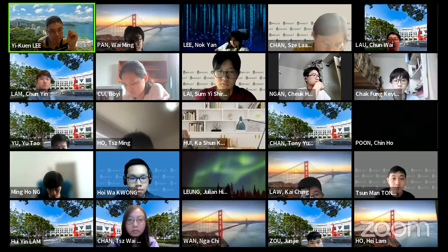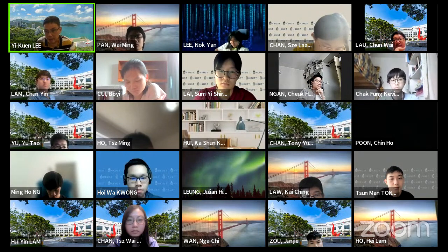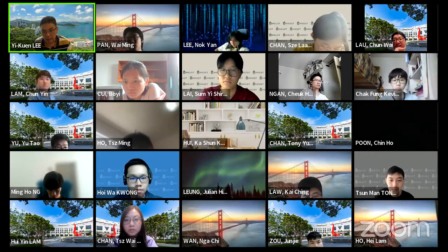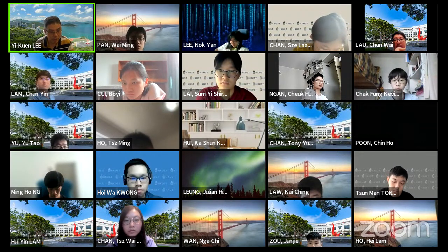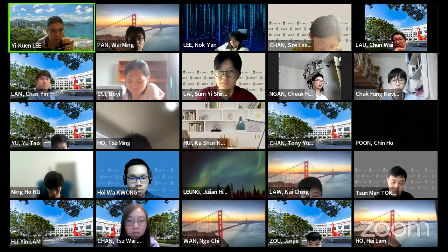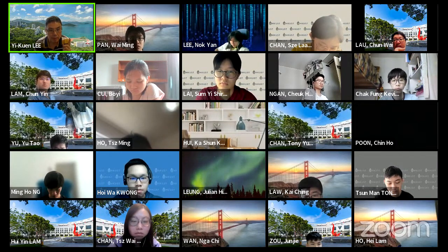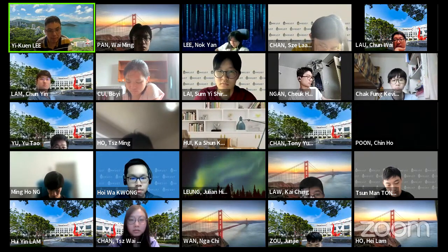Some percentage of people will not be happy about this human thermal comfort index (PMV). That's why the model not only predicts the average human thermal comfort index, but PPD also tells you how many percent of people are dissatisfied.